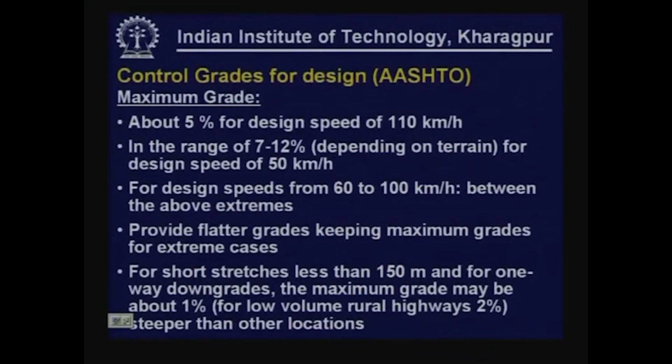Now, there are certain relaxations. For a short stretch of less than 150 meter and for one-way downgrades, the maximum grade may be about 1% steeper than at other locations, and for low volume rural highways, it may be even 2% steeper than at other locations.